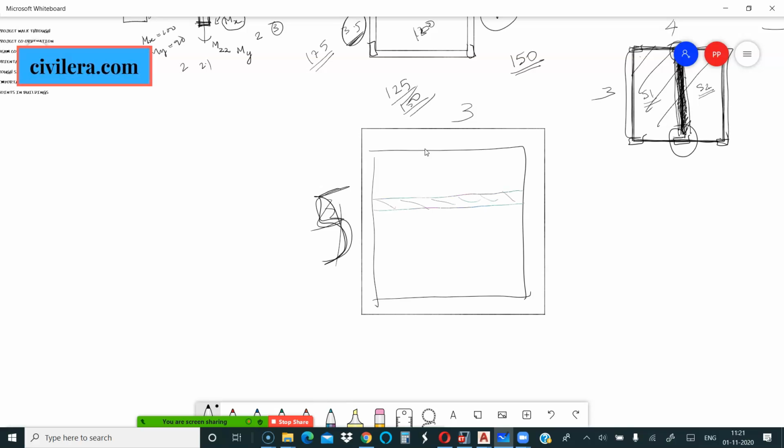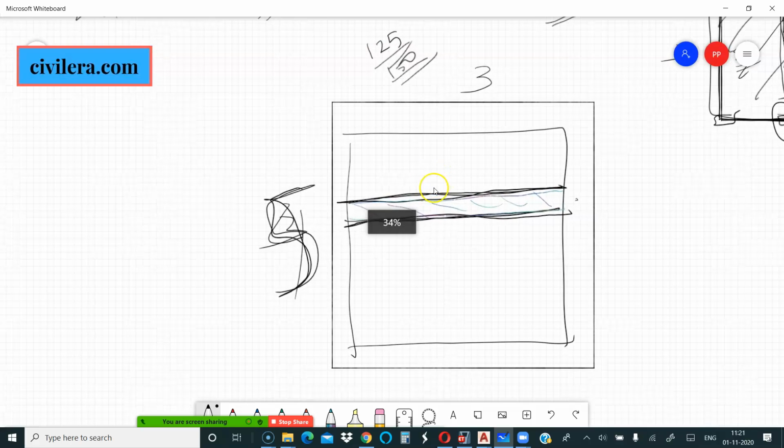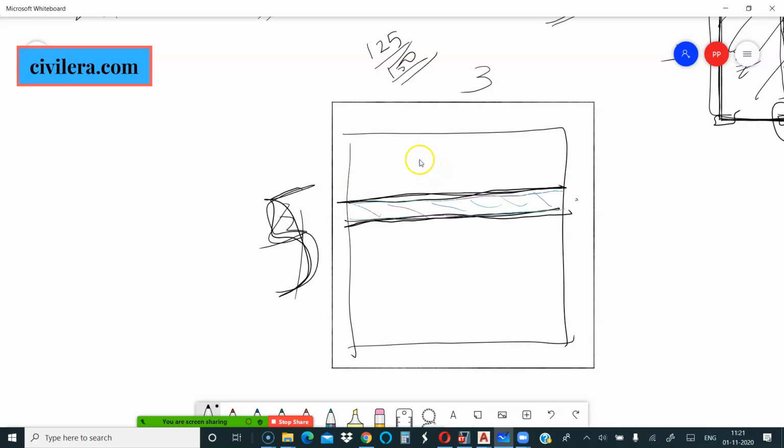Ideally, I would like to see if I can give a beam here so that the concentrated line load of the wall is taken by the beam and then transferred onto the other. But it's not 100% needed. Sometimes you may be able to put the load onto the slab. Only thing is that again you may have to give a concealed beam here to distribute the load, or you may have to have higher thickness for the slab, things like that.